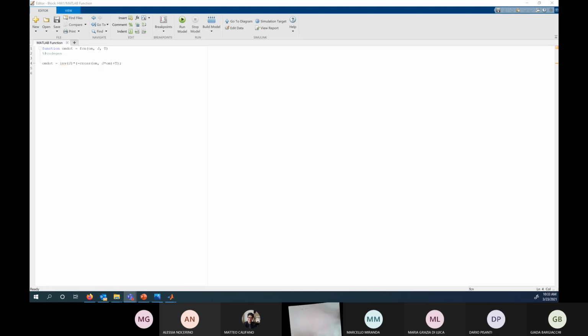So what is that equation right there? That equation is omega dot, and this is in vector form, right? Equals the inverse of J, so J minus 1, multiplying minus the cross product of omega and J omega. This is a matrix, this is a vector, plus T. T is what I called moment before: torque, M, same thing.